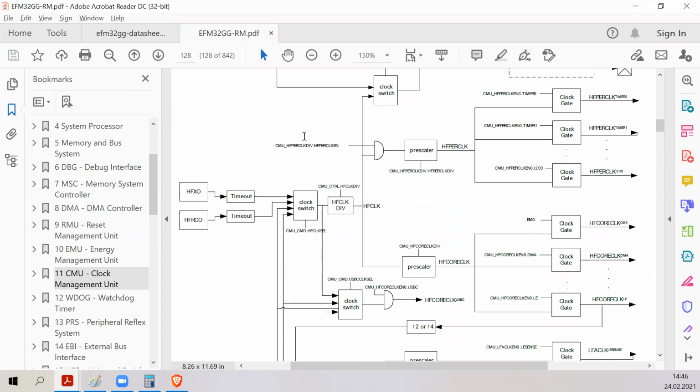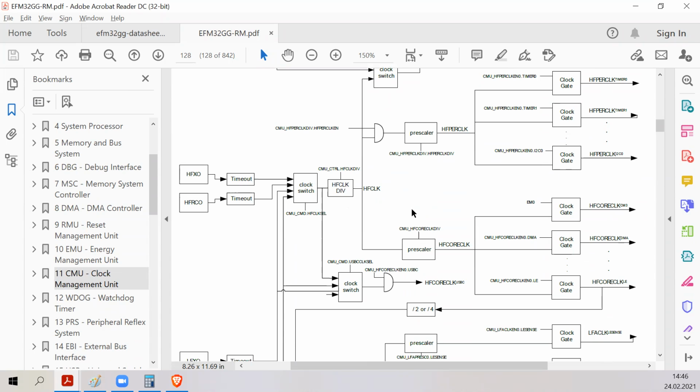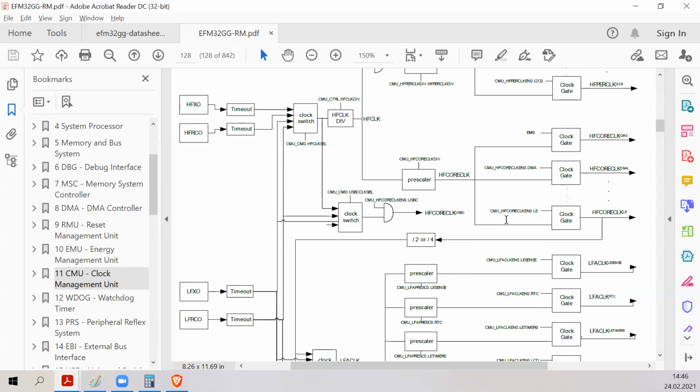So if we are using printf to print out messages and we put microcontroller to sleep, also printing out messages stops. It's not really that bad because usually when microcontroller sleeps, nothing happens, so we don't have any messages to send. But in general, if we want to send the messages, the CPU is in active state, sending information.